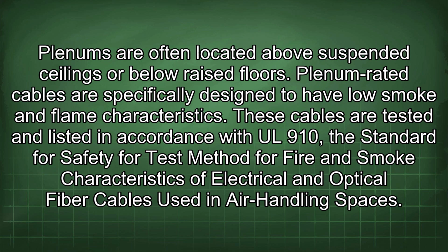Plenums are often located above suspended ceilings or below raised floors. Plenum-rated cables are specifically designed to have low smoke and flame characteristics. These cables are tested and listed in accordance with UL 910, the standard for safety for test method for fire and smoke characteristics of electrical and optical fiber cables used in air handling spaces.